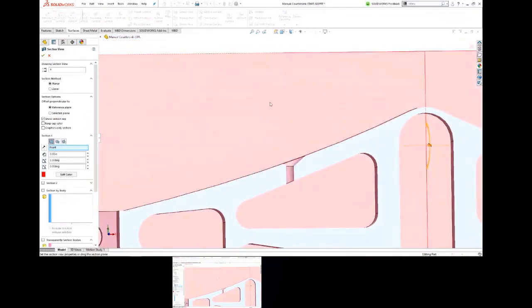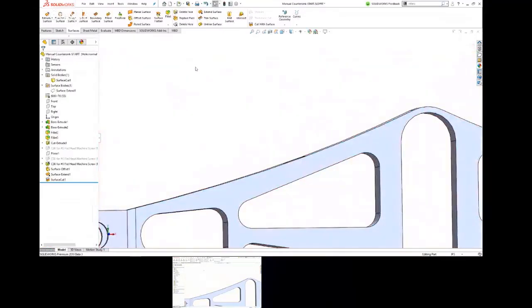If you delete it, it won't destroy the feature? Good question. If I delete the surface body, doesn't that delete the feature? In this case, no, because that's a time-dependent feature. When I do a delete body, that becomes a time-dependent feature that happens after it was used. So I'm deleting that body after it's served its utility. And if you're a hardcore surface modeler, anybody here that does a lot of surface modeling, that's a pretty standard technique. If you have a lot of surface bodies that you've created that no longer serve a purpose, you go back and do a cleanup operation by deleting all those bodies that are no longer needed.